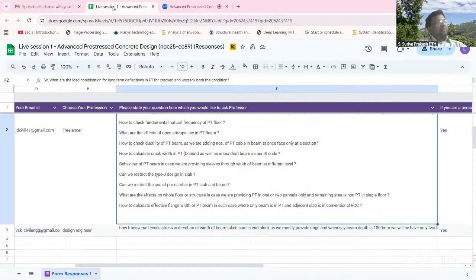In my advanced RC course in NPTEL, again, you can look at some of the analysis that we have done, but that's slightly different, but you can understand the concept, okay? S is the crack spacing, which depends upon how good is your bond of the pre-stressing, the rebar, what is the spacing of the rebar, what is the diameter of the rebar, how much is the distance of the rebar, all those parameters are there. So I can share a PDF document from Collins and Mitchell. There is a book